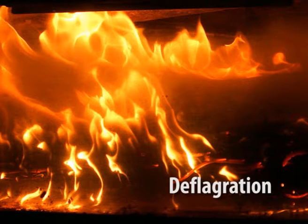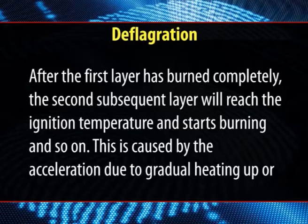Next is deflagration. It includes rapid and violent burning and is an intermediate step between gradual combustion and detonation. Deflagration can also be understood in simpler terms as comprising of layer by layer burning phenomena, wherein the lower layer of the propellant reaches the ignition temperature and starts burning.